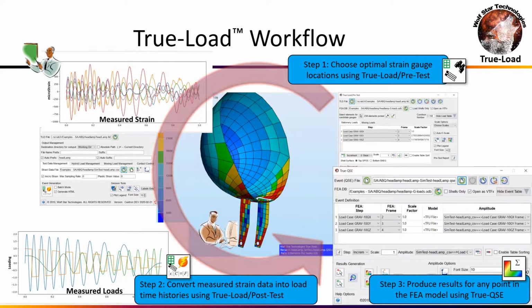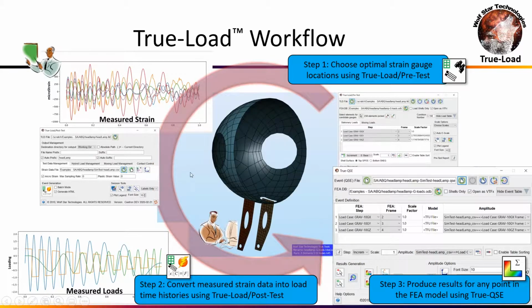So all we have to do is go back into the FEA model and we can remesh the part. So here I made some design changes, put some holes in this thing, thicken things up. And the only requirement I'm going to put on you now is that you have to solve it with the same unit load cases you started off with. So these are very simple solves, just 3 unit load cases. So you solve these 3 unit load cases.